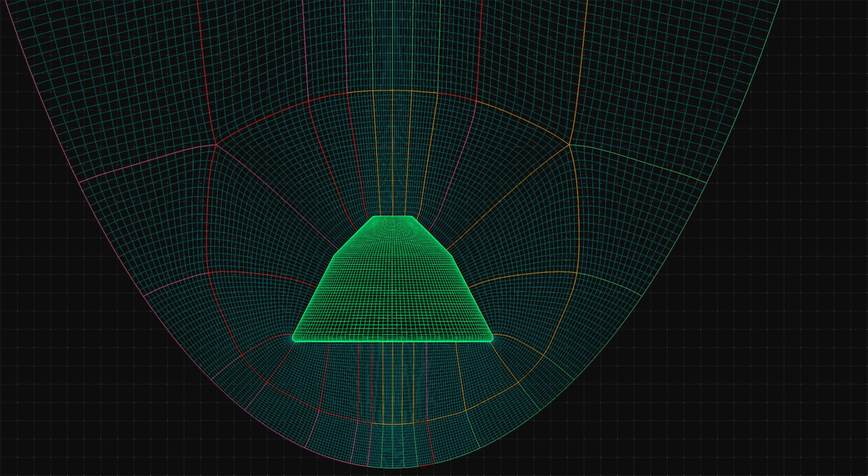The grid smoother essentially restarts from the baseline grid, and its computational power is concentrated on accommodating the new surface variation. The rest of the domain retains its smooth, high-quality grid, saving us valuable processing time. This technique is incredibly useful when you are iterating on designs and exploring different geometric configurations.